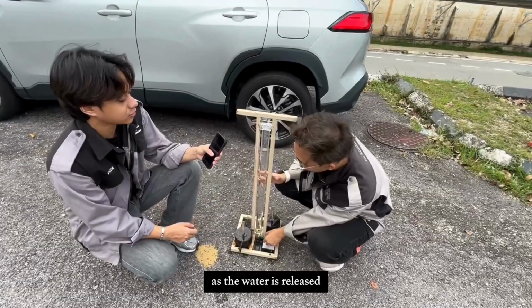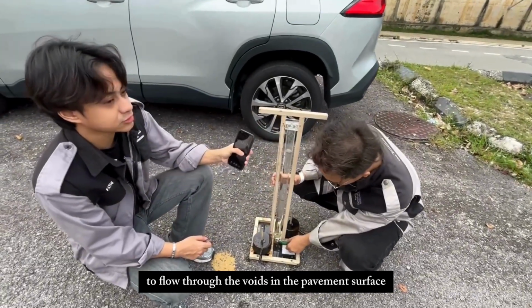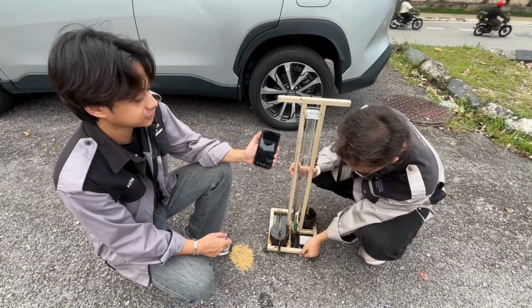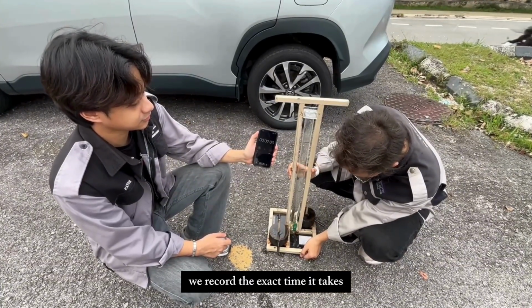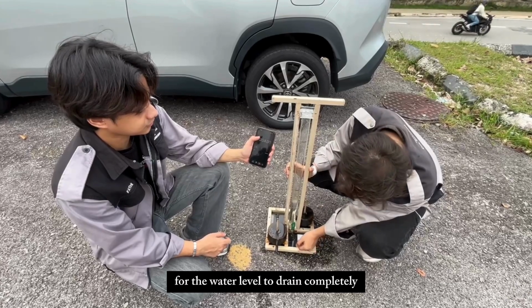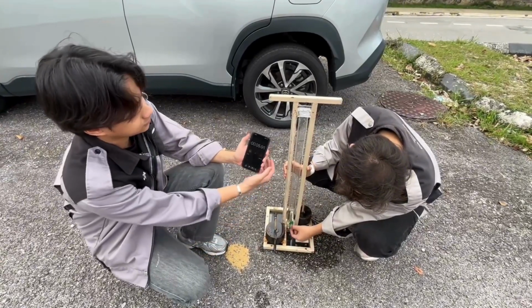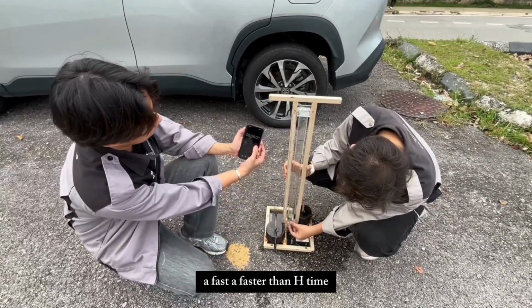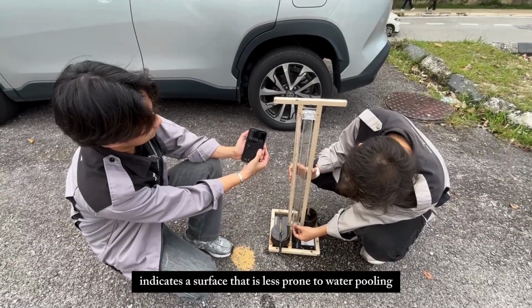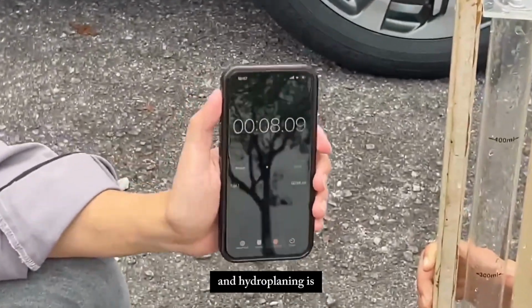As the water is released to flow through the voids in the pavement surface, we immediately start a stopwatch. We record the exact time it takes for the water level to drain completely. A faster drainage time indicates a surface that is less prone to water pooling and hydroplaning risk.